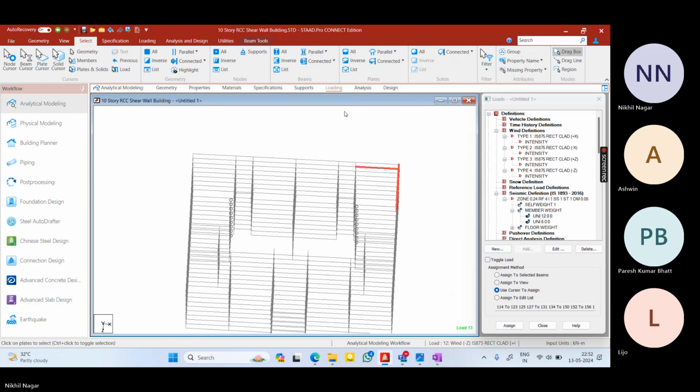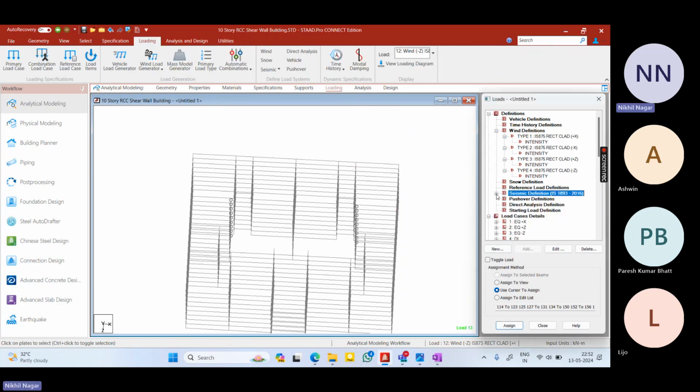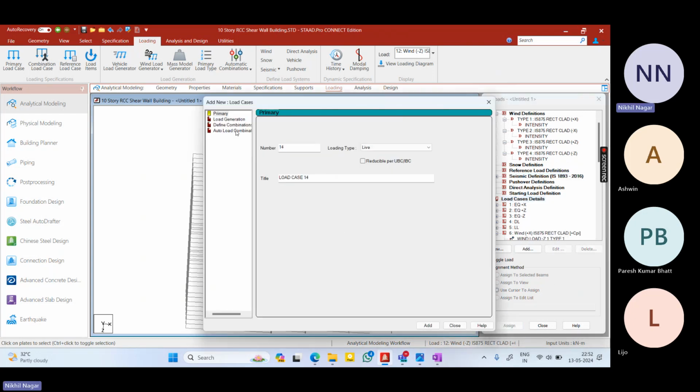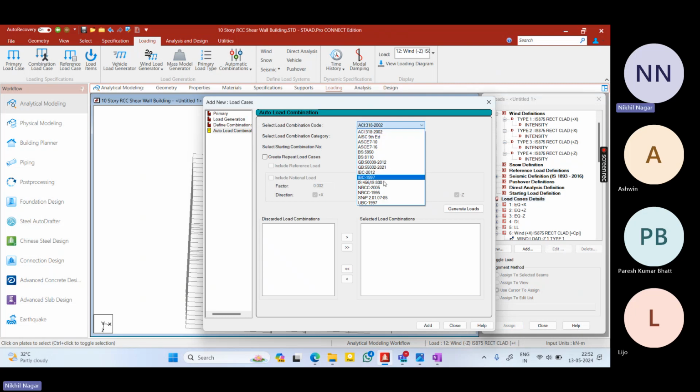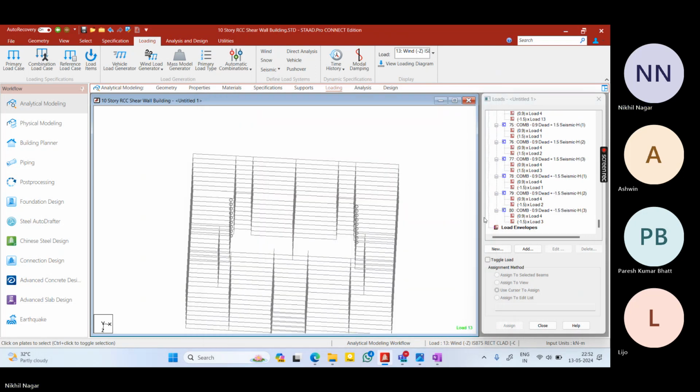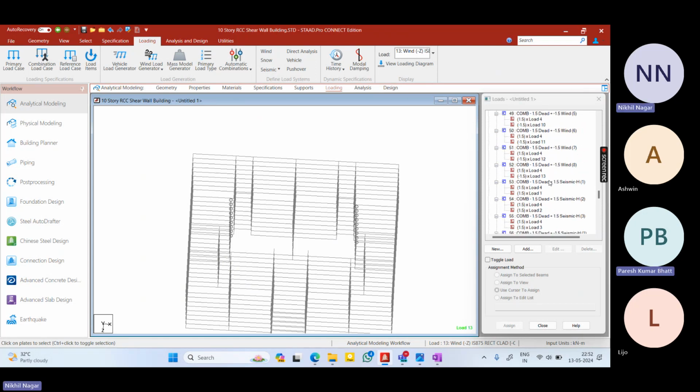Now it is done. Now you can just make your load combinations. By auto load combination, click on add. Choose the code. Table is okay. Generate load. Okay, so now if you see that...